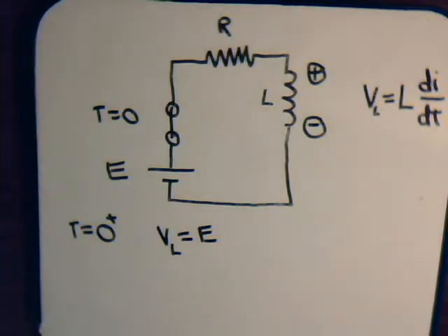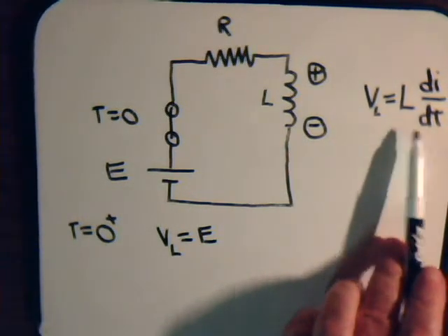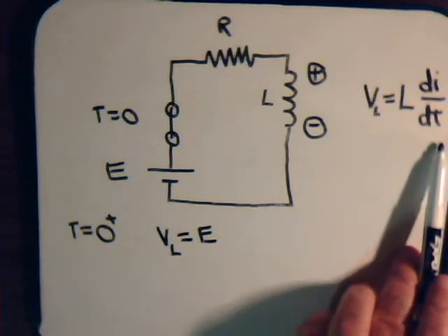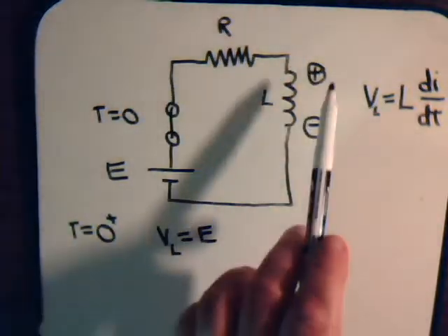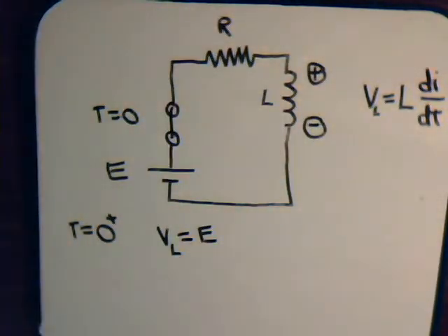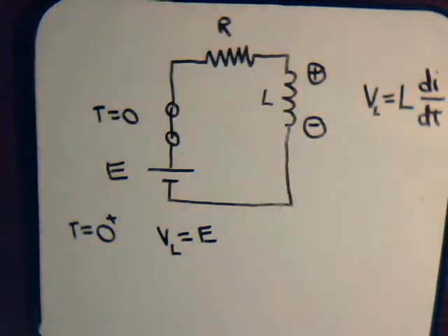Now, the expression for the voltage across the coil is its inductance times the rate of change of the current, and its polarity is such that it opposes the flow of the current into the coil. That was just Lenz's law. We write this induced voltage with circles around it because this is not a voltage drop now.